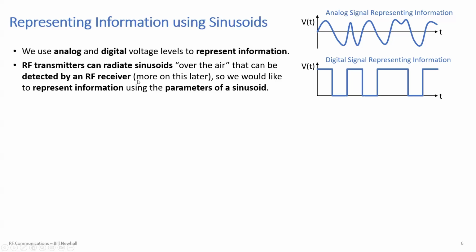And we'll talk a little bit about antennas and frequency spectrum, but basically, within a certain frequency range, you have reasonable antennas that can convert the conducted power to electromagnetic waves, and there's a frequency range of that sinusoid that results in realistic sizes of antennas, because antenna size is related to wavelength generally.